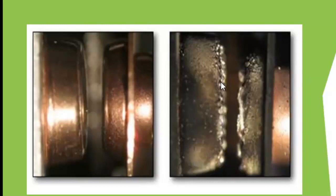It can destroy the circuit breaker contact. And at the end of the day, we'll have the formation of metal oxide that will increase the resistance at the contact, okay? So remember that as the arc is forming, it can lead to the oxidation of these metals, okay?